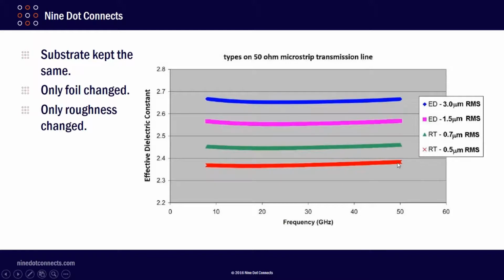So the dielectric constant is the smallest and actually will be closest to what would be referred to as the bulk dielectric material's property. The higher RMS causes a higher effective dielectric constant. And the interesting thing about it is if you start doing any modeling in electromagnetic simulators, you'll need to understand that this conductor roughness will change what dielectric constant you want to use in your simulations.